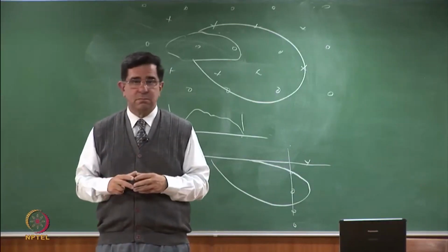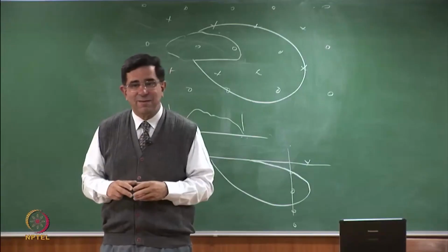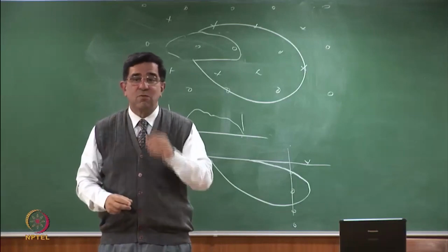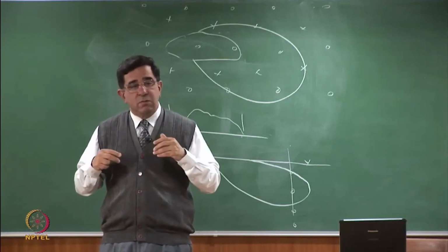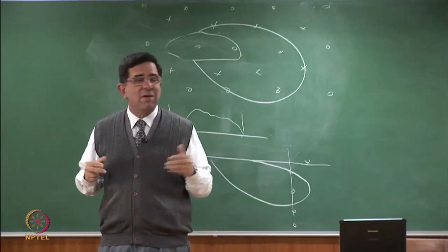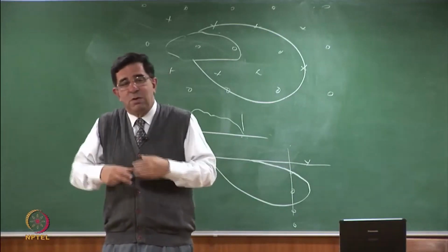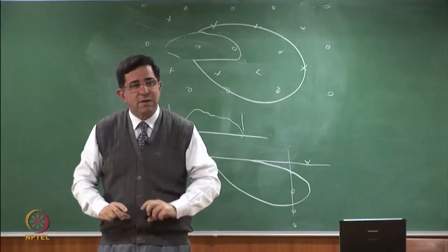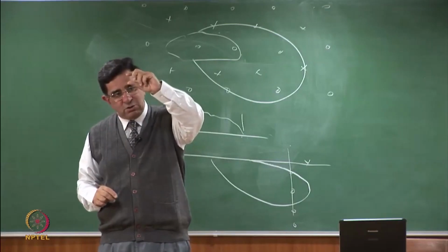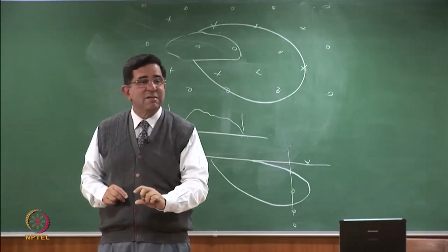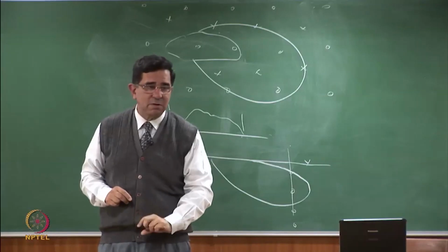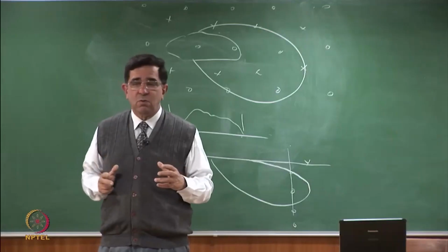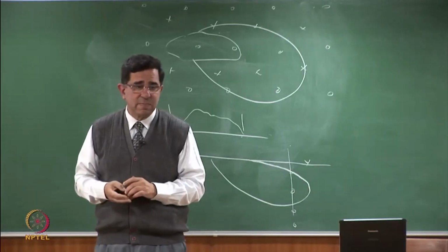The multi-port groundwater well is the cutting edge for taking samples in one borehole from different depths, whether you monitor it once a month. You see, the groundwater doesn't travel very fast, I have already told you. So you may monitor groundwater only once a month, but at least you are able to pick up the samples from the different depths, and you know there is no contamination at the top, but you are getting a slight increase in reading at mid depth and there is no contamination at the bottom. And with these devices, you can monitor your old and new landfills.